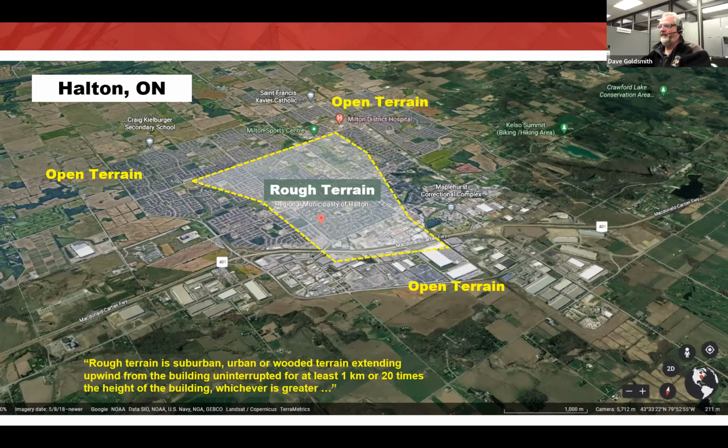We certainly saw that. Historically, sliders were designed for 300 pascals and a little change in the back pocket. Under the new system where it's 290 or 330, you've got more change in the back pocket at 290, but at 330 you're right brimming and very close to overflowing because you originally designed it for 300. You don't have that extra leeway anymore.